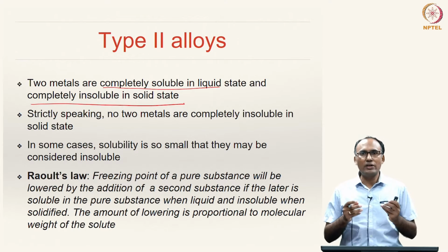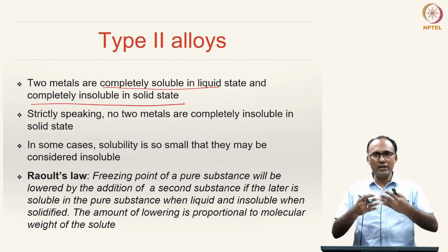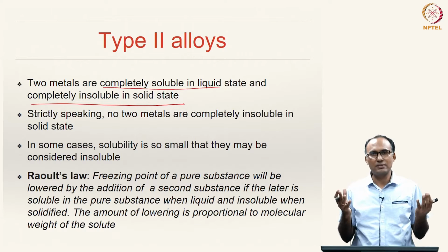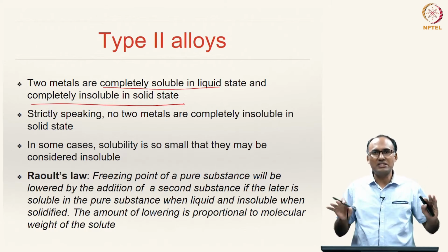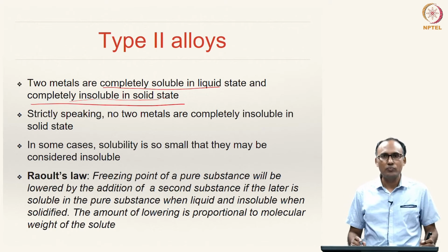That means, in the liquid state, they are a nice liquid solution, but when you are solidifying, after solidification they separate out into two different components. They will not make a solution, they segregate into A and B separately. That is what you mean by complete insolubility in solid state.